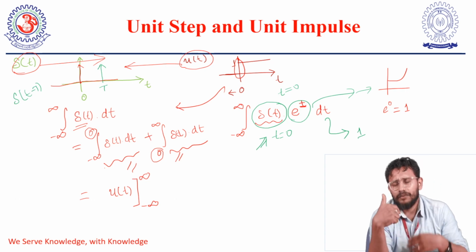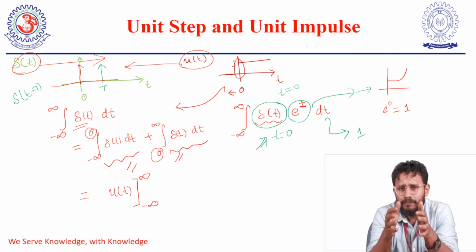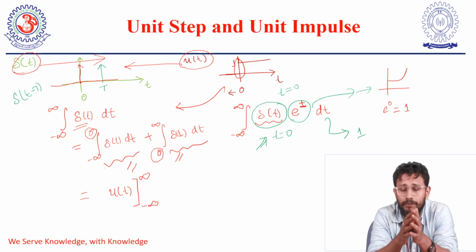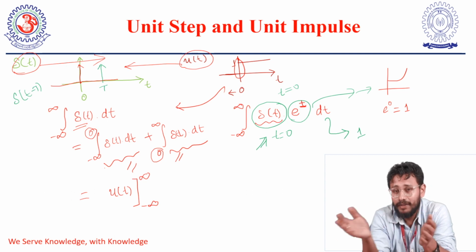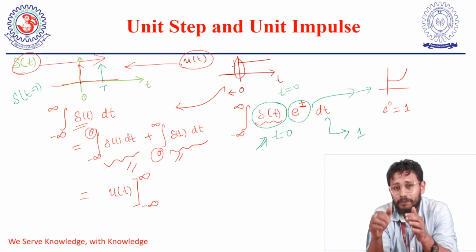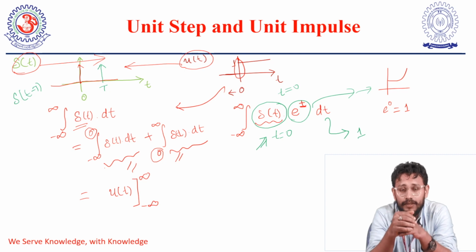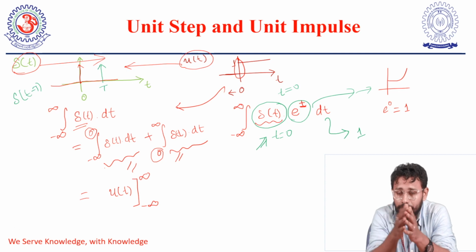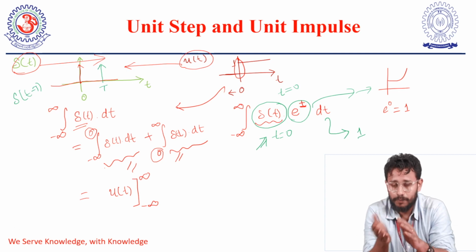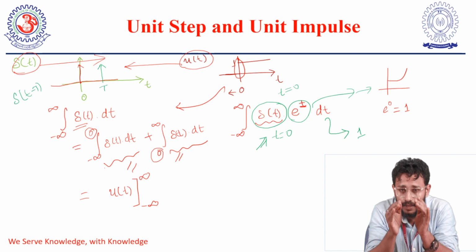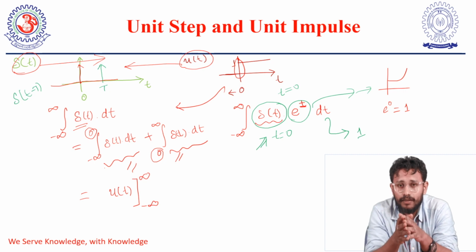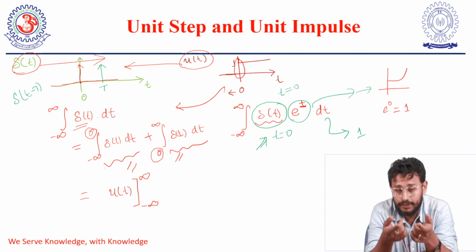Now, what we are willing to do is observe a system or design a system, define the dynamics of the system in terms of ordinary differential equation, use Laplace transform, make it into simple mathematical expressions, and then try to apply these types of inputs there, unit step, unit impulse, and try to observe the response of the system. Now, if I observe the unit impulse response of a system, this technically would be the same as the basic response of the system when the impulse function alone existed.